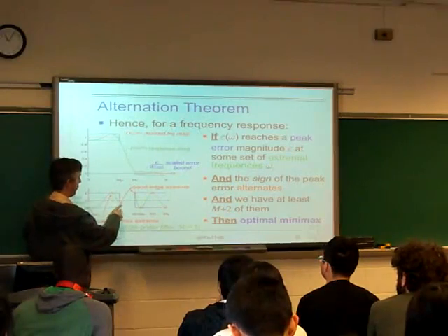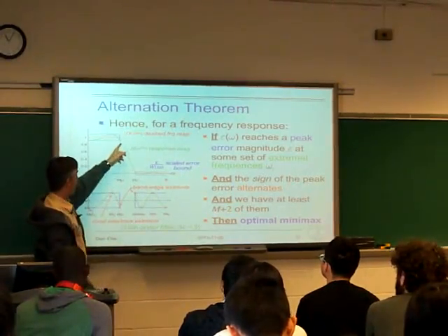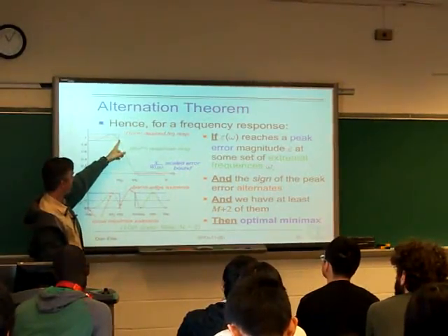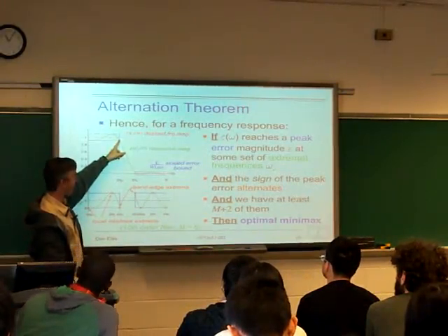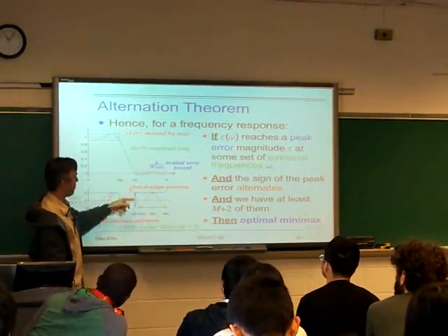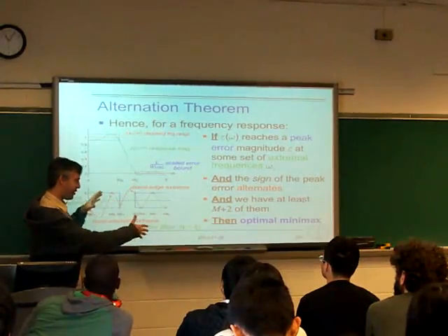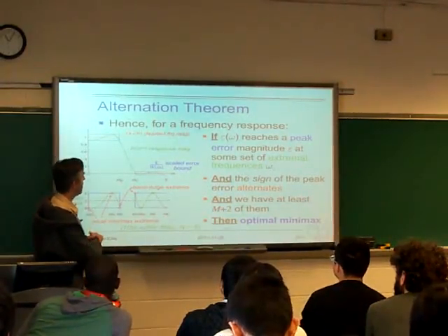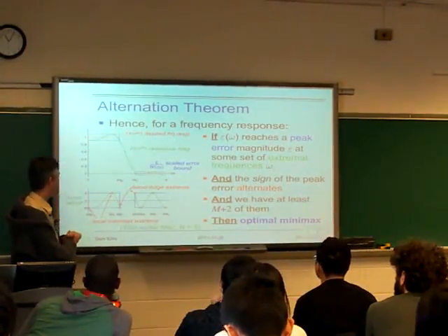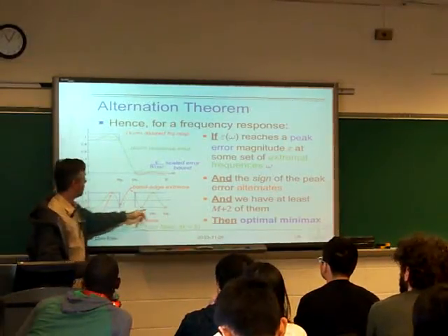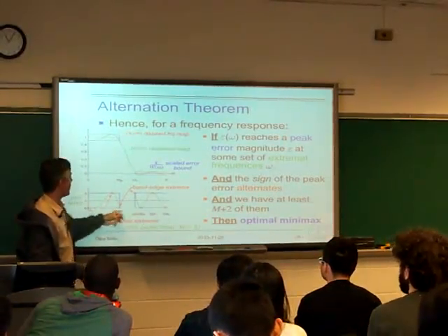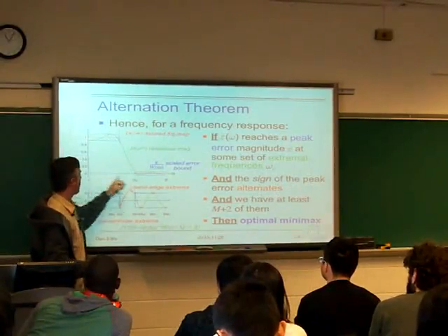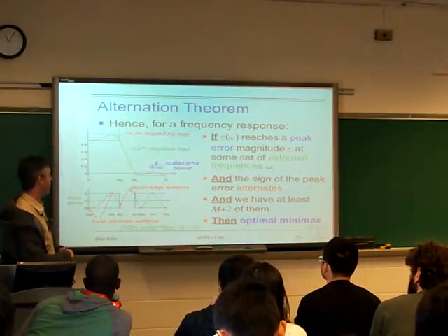We also get 2 from the band edge, right, because the optimal filter is always going to just touch that band edge here and just touch that one, because if it didn't, then we'd be able to make the transition band a little wider and still keep within bounds. And we also get points of extrema at the 2 edges, the 0 frequency and frequency pi.